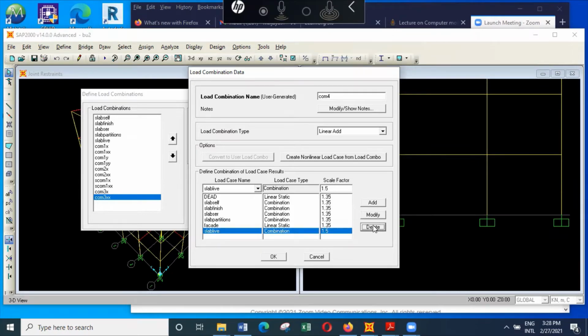And then I also want to highlight another fact. Now when you look at the live loads, when you have a multi-story structure, a certain reduction in the live load is allowed. So if you have more than 2 floors, you can deduct 10% of the live load. If you have more than 3 floors, you can deduct 20%.